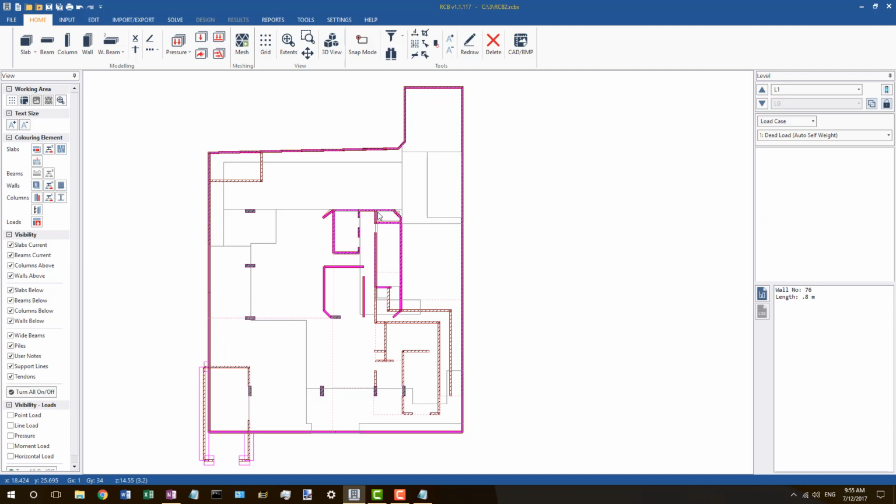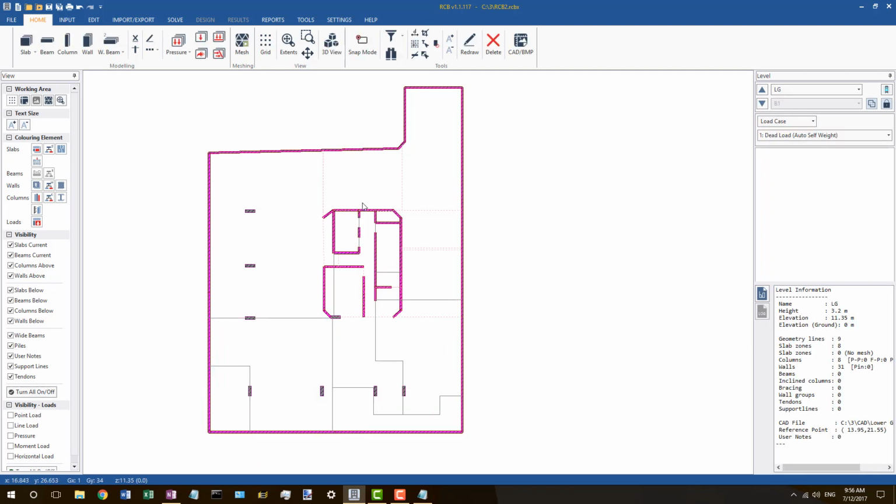So summary of the key points: the key elements are the walls. So we should basically fix the walls once, never have to fix them again. We don't want to be chasing our tail. So starting from the lowest level, we fix the walls and then align everything up to them, being other walls, geometry lines, columns, if needed as well, to the wall elements. Important thing to note, wall elements are the key elements because they're meshed to above and below a certain floor, and they're also the most complex element in the software, hence they're the element that can cause the most errors during the analysis.